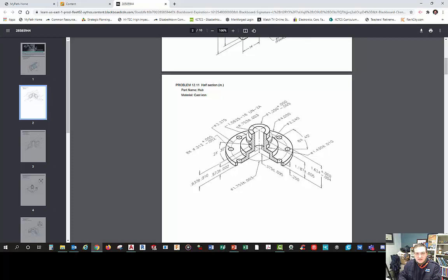the paper size and the paper orientation is all of your pages are set up landscape, which means the long dimension is running X, horizontally. Well, that means that your view should be laid out horizontally. A section view or section drawing typically has a front and a side view, unless it's another variation where you're doing a broken out section or something else.